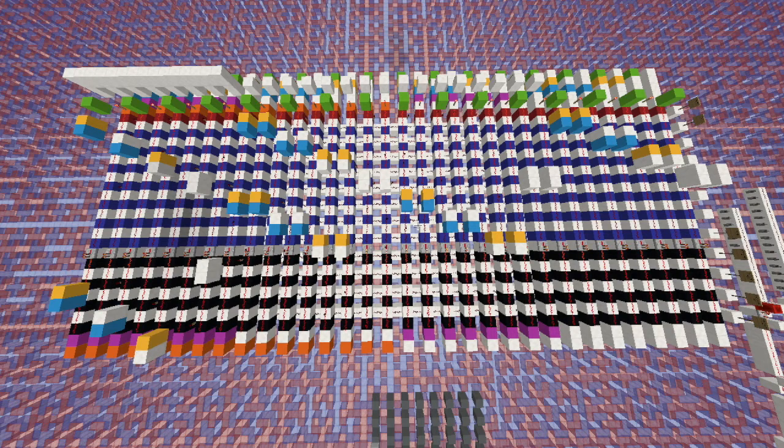So the number of times that you need to shift the overflow bits to the right is the problem. If you rotate once to the left, then you need to rotate the most significant bit 7 times to the right so that it arrives at the least significant bit. So if we want to use the same decoder to code the right shift instructions as the ones for the rotates, then the counting has to be reversed for the right shifting ones. This is going to be a bit inconvenient, but it's ultimately something that we can just deal with.